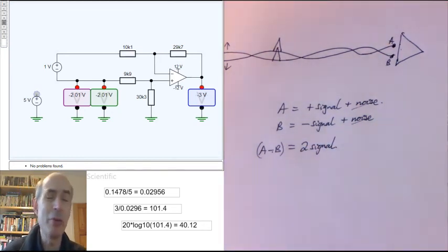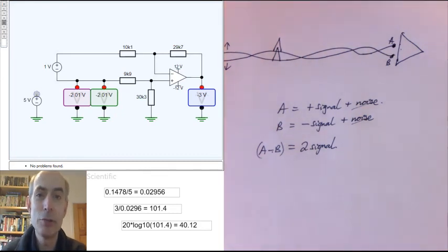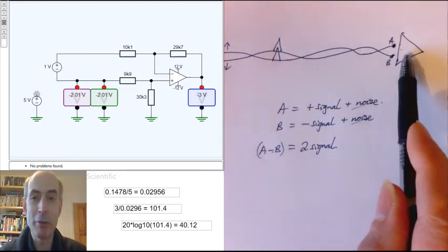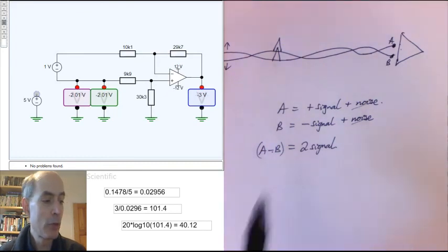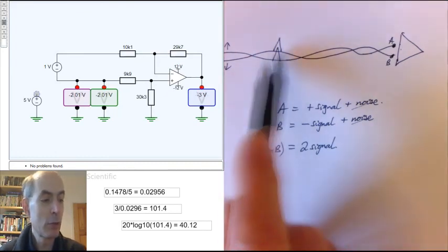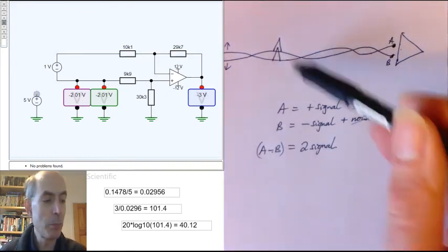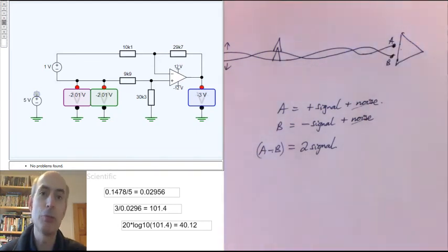It's a very common and very effective way to reduce the noise that's picked up on what can be quite long microphone and instrument cables. But of course, to work, we do need an amplifier with a good common mode rejection ratio, so it does eliminate these noise spikes, any signal which appears on both of the input wires. Next time, we'll look at the input impedance.